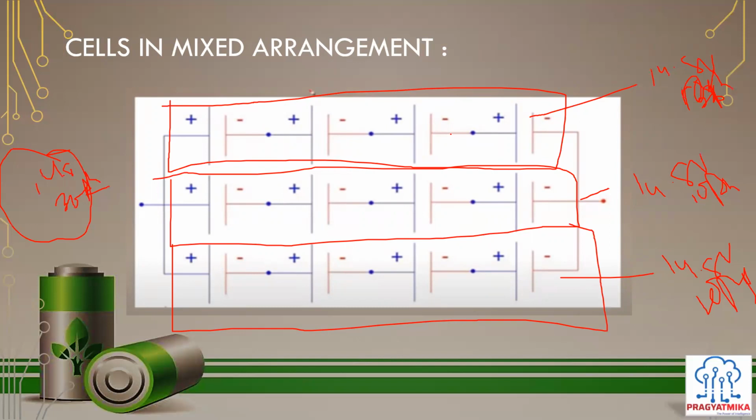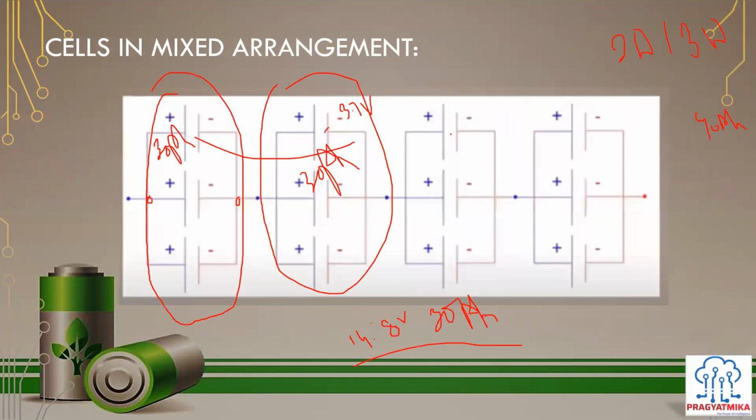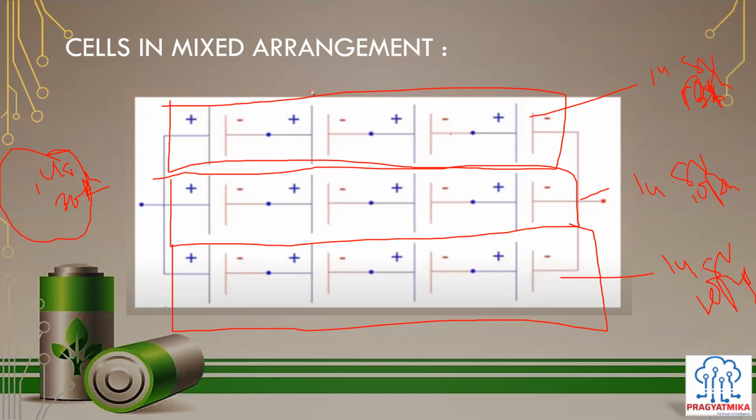You have raised a point related to balancing, so that is a valid one. Can you explain a little about the balancing? So, sir, one would be electrical balancing. If all the cells are connected in series and equal current is not drawn from those cells, one of the cells might fall below the required capacity before the others, and it might cut off the series altogether according to the BMS. But if constant current is drawn from all the cells, that is the ideal scenario. That is one part.